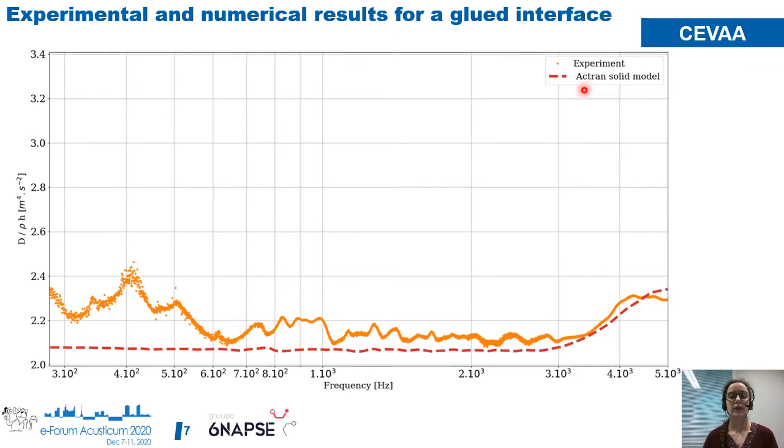The numerical and experimental results are close at high frequency. There is a rigidity change at 3500 Hz. Our hypothesis is that the effect of the foam changes with frequency. At low frequency, the foam is viewed as an added mass, and at high frequency, it is an added spring.